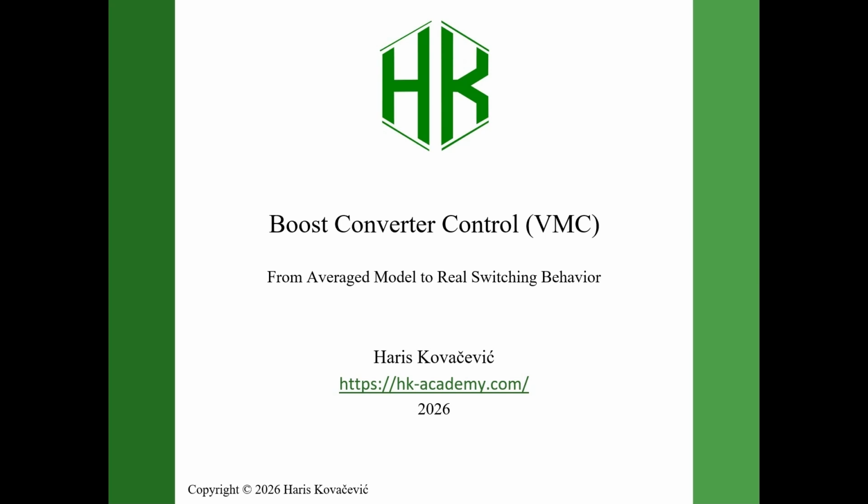Most engineers assume that if a boost converter looks stable in an averaged model, it will behave the same in real hardware. But that's not always true. In fact, the moment you include switching effects, you often get larger voltage deviations, slower response, and sometimes even instability. So the question is, can you really trust your averaged model?